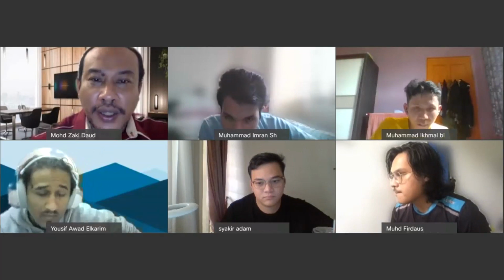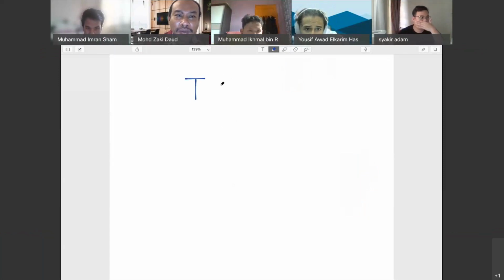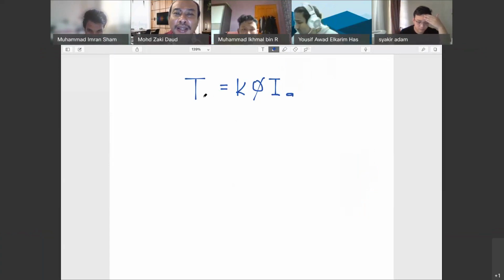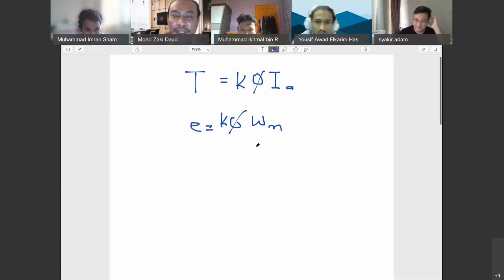I share. Okay, like I told you, for the DC motor, can you see my screen? Yes. So for the DC motor, there are 2 equations, right? T equals K-phi IA, right? Okay, that means T is proportional to I. And then you got E equals what? K-phi omega M, correct? These are 2 important equations for the DC motor.